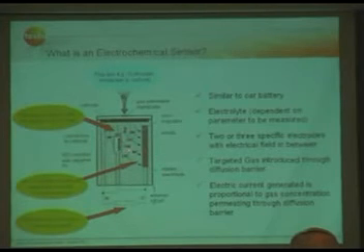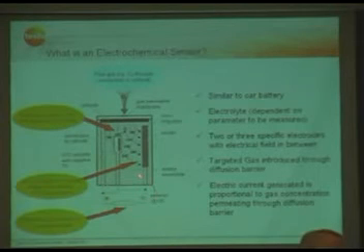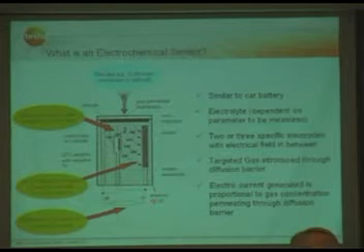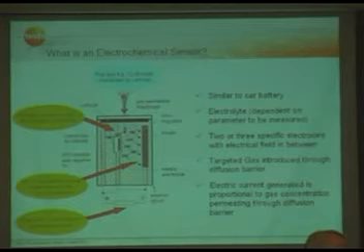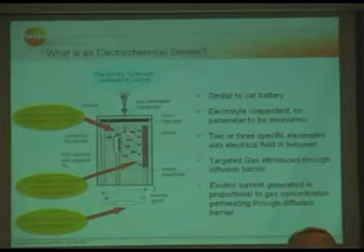When they migrate to the anode, a little current is produced proportional to this migration, and all we do is measure the voltage across a resistor. And this is how you can measure O2. There are several different sensors available, but this is the way we do it.